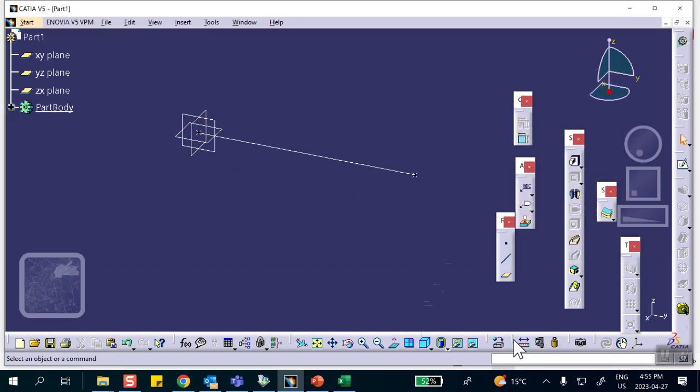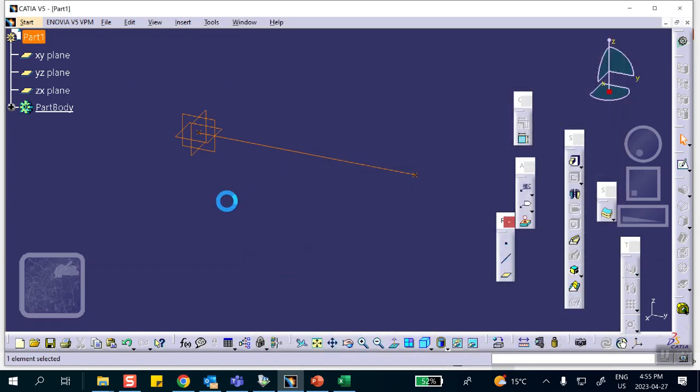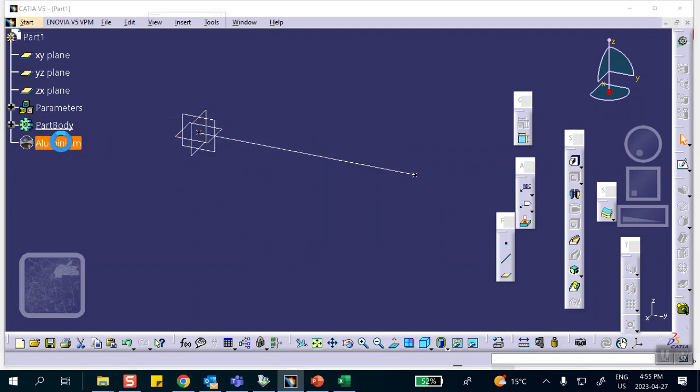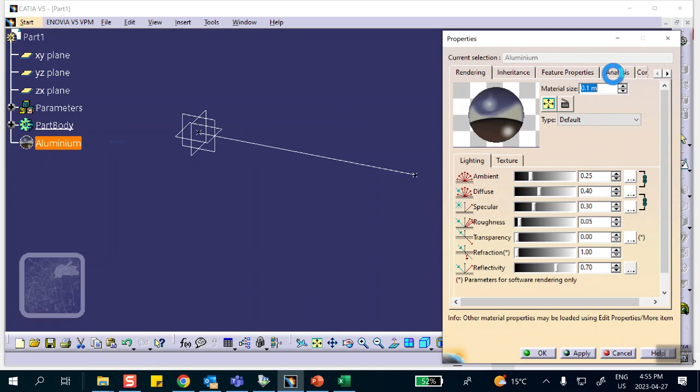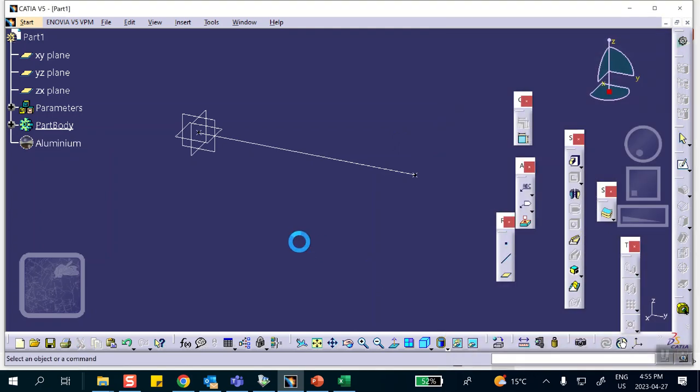All right, let's apply material properties to this. I'm going to use the dummy aluminum applied to that. The actual material is irrelevant as long as you make it a very small stiffness and mass, a very small density. So the Young's modulus for aluminum is 70 GPa. I'm going to make it 0.1, which is pretty much nothing. And the density of the aluminum is 2,700 kilogram per meter cube. So I'm going to make it 0.1 so that these will not affect my spring properties.